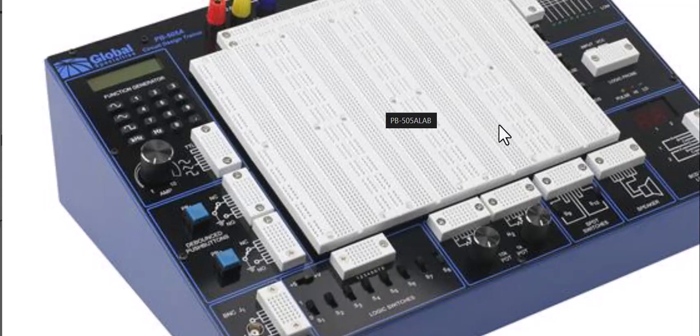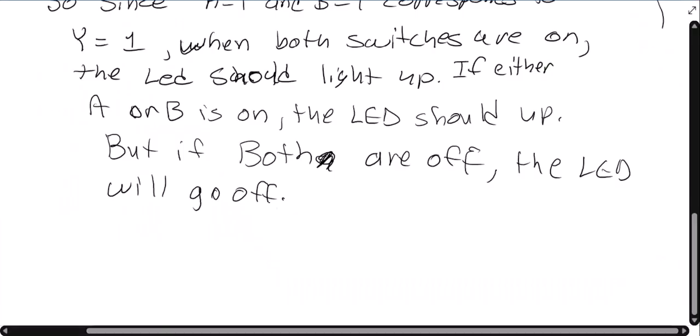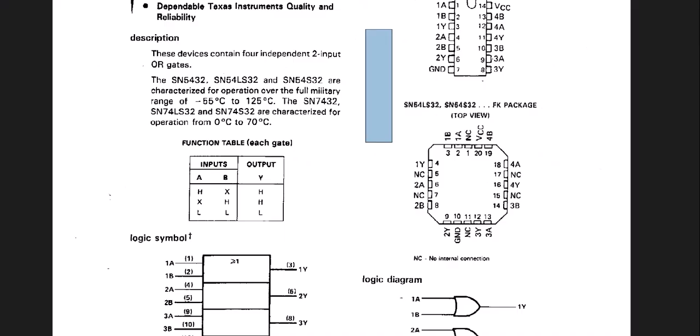Okay, so let's say you have the chip in right here. You would attach pin 1 to switch S1, pin 2 to switch S2, and pin 3 to an output that would be on here somewhere. Then you can just flip the switches and see if it operates according to the logic table. Does that make sense? Okay. All right. And then let's see what's next on your lab.